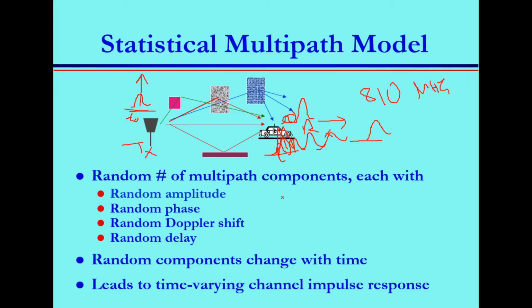So this is in words, conceptually. But now mathematically, how do you model that? Response of the channel at t to an impulse at t minus tau. This is the impulse that you send, for example. When you send this to the channel, it affects its amplitude A, its phase phi n of t, and delay at a different time. And this phi actually ultimately causes the Doppler shift.